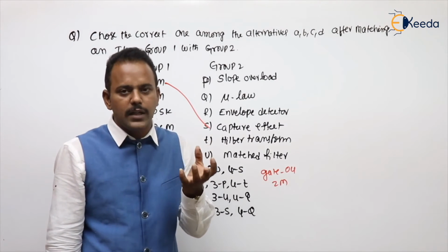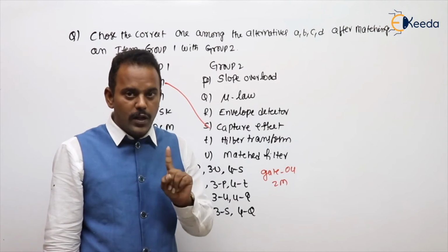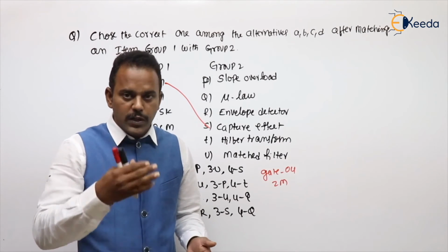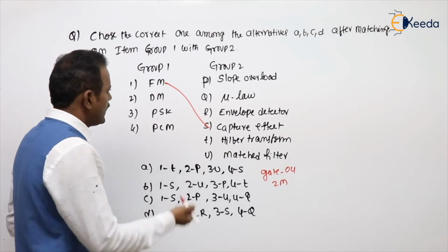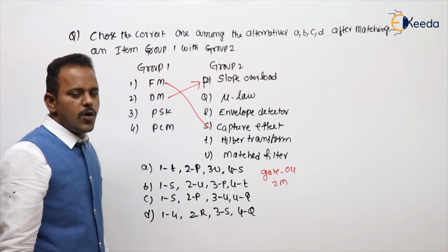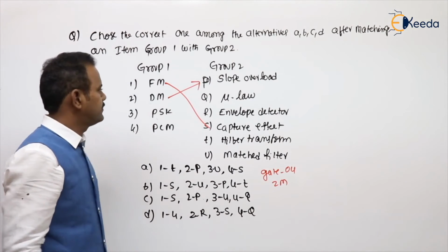That is one of the properties of FM. But in AM, both will mix. In FM, only the strongest signal will come. If both fluctuate, FM also fluctuates between the two. So FM is the capture effect. Next, delta modulation, we already saw. In delta modulation, there is slope overload and granular error. Granular error is also called idling error.